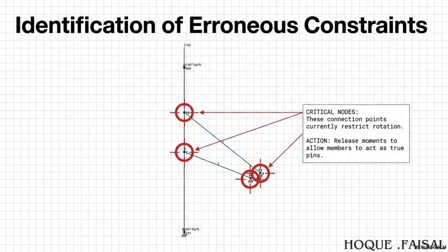It really does. It's a workhorse of heavy construction formwork. It's a very stiff, very strong steel beam. That's the main vertical part, the 24-foot mast of our sail. And then to prop it up, to keep it standing, we have Section 3, which is listed as HS102 by 6.4. Which is just engineering shorthand. It stands for a hollow structural section. Basically, a round steel pipe, about 4 inches in diameter.